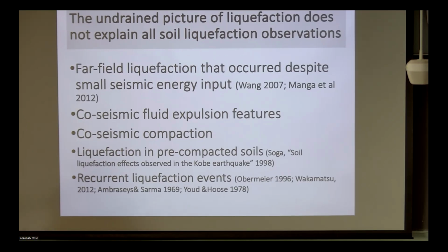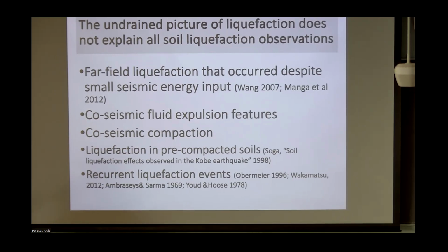There's reclaimed land, and in order to make it resistant to liquefaction, because we know that liquefaction occurs mostly in loose soils, there's a process that the engineers do, and that is to vibrocompact. They go with this vibrator, which is huge, and they compact the soil. And then they get to some compaction, they say, okay, now liquefaction won't happen, and we can build on it. But then this reclaimed land actually liquefied in the Kobe port in the 1995 earthquake.